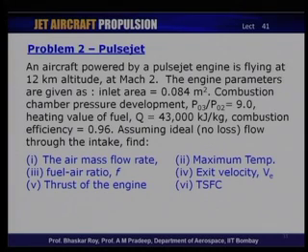The heating value of fuel again is given, Q is equal to 43,000 kilojoules per kg, and the combustion efficiency prescribed is 0.96. Again, assume that it is an ideal flow, that means there are no losses through the ducts or the intakes, and assuming that kind of a lossless flow situation, find the air mass flow, the maximum temperature, the fuel air ratio, the exit velocity, the thrust of the engine, and the TSFC, the performance parameters. So, let us see whether we can find all those performance parameters using the prescribed values that have been posed here in this problem statement.